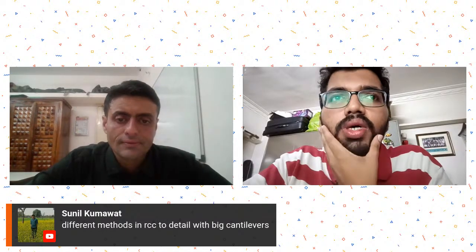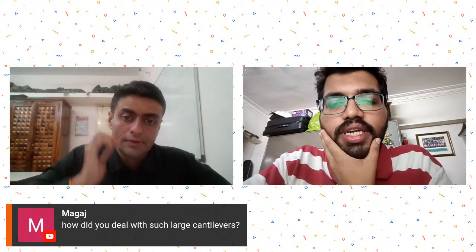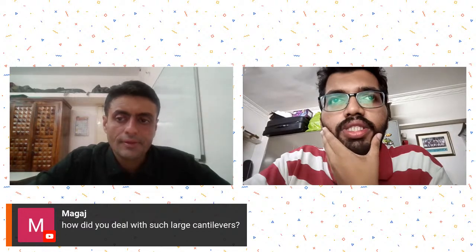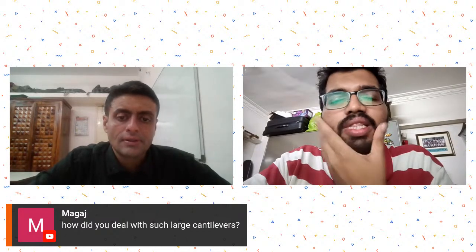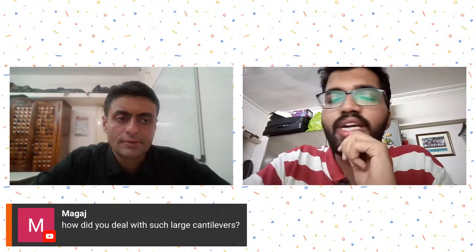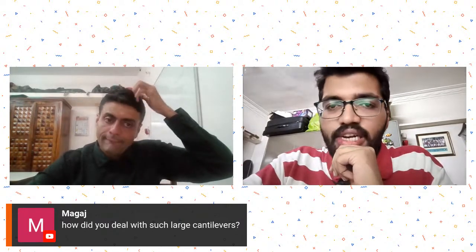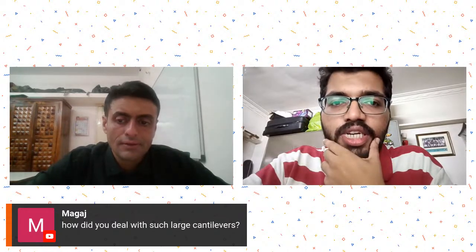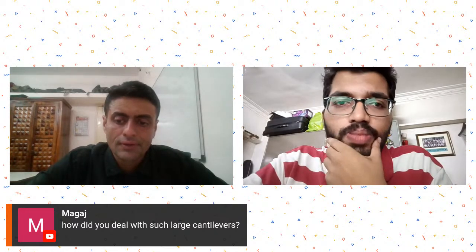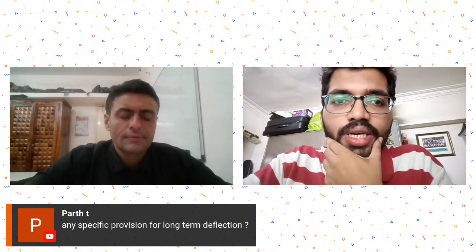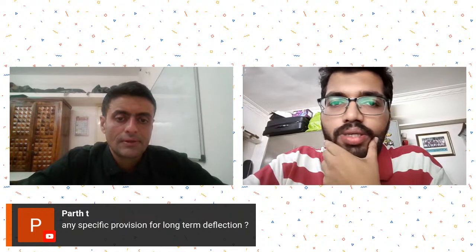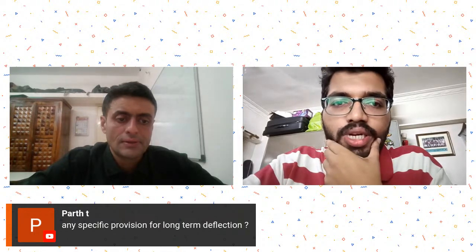So the main thing was the deflection actually. Other than that, we check it. It's modeled as a shell element in ETABS itself, as a deep girder, which is nearly 3.6 meter in height. So the moments and the shear forces are checked, and the design of the girder is checked.